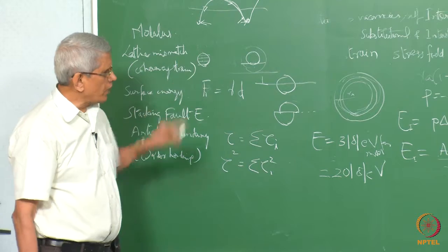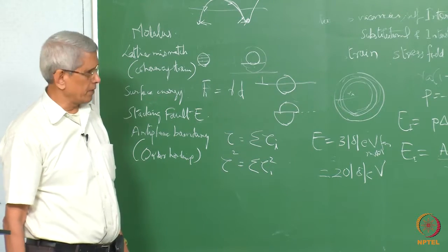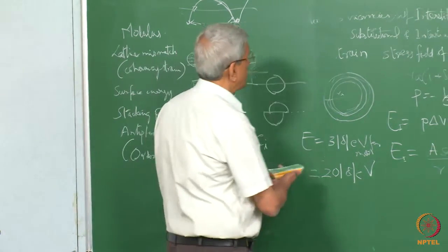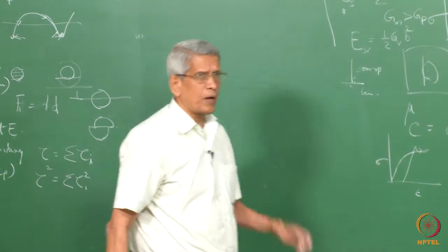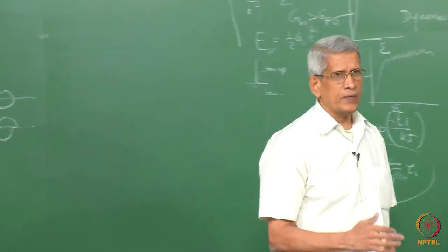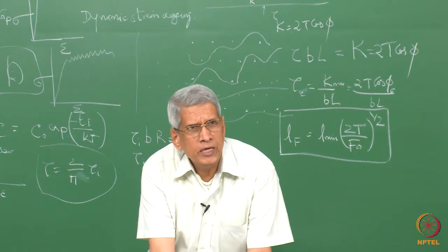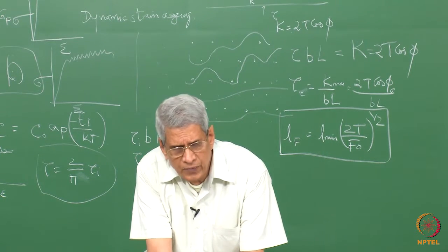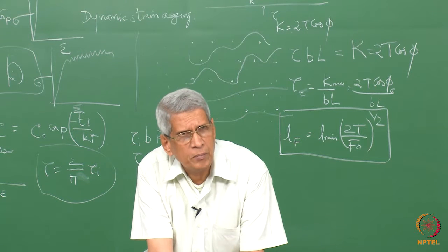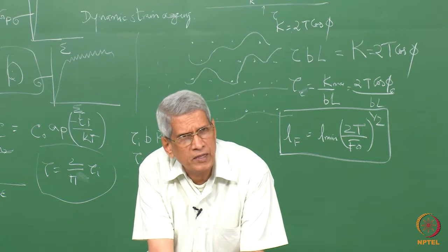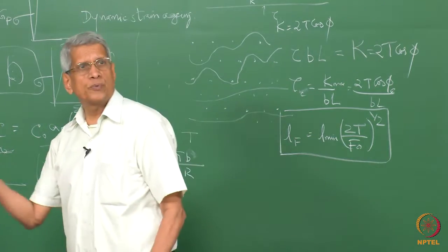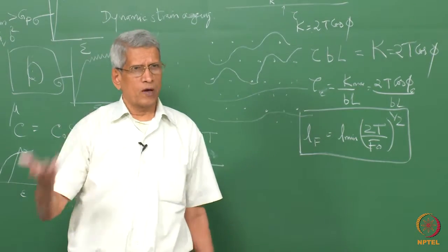Suppose ordered particles are there. What happens when the first dislocation passes through the particle? It disorders it. Depending upon the crystal structure difference between the matrix and the precipitate, groups of dislocations have to pass through.